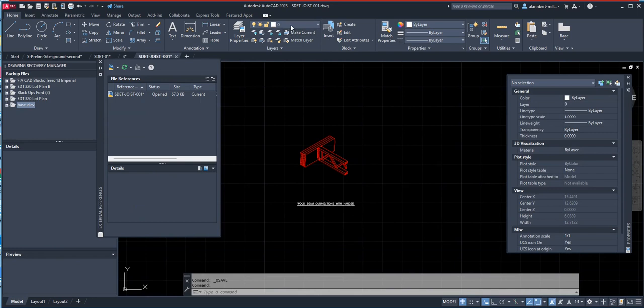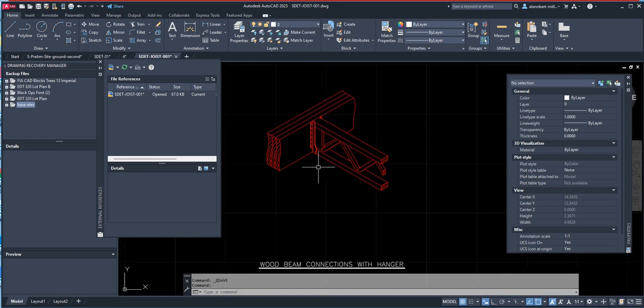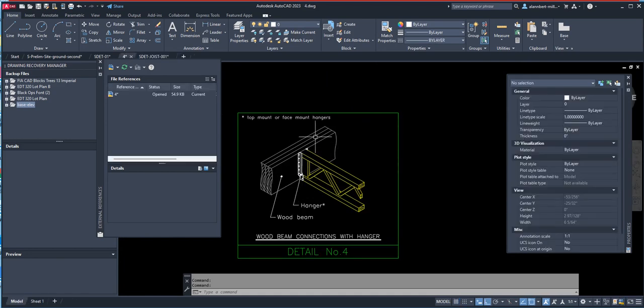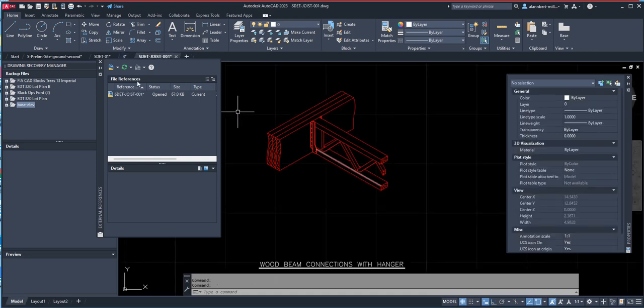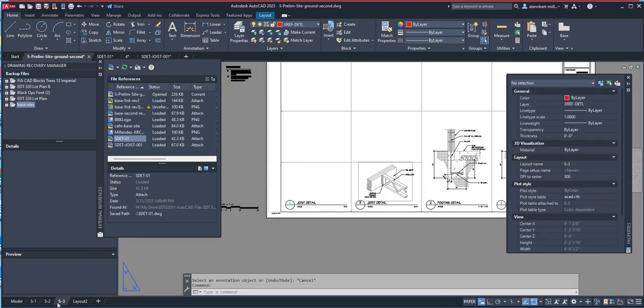Create a layer called Pen 1, change everything to Pen 1, remove the arrows like we did on that other drawing here. This is the original downloaded detail. We removed the arrows. We made everything red, and then we added these leaders and notes, not on this detail, but when we actually inserted it on our S3 detail here.